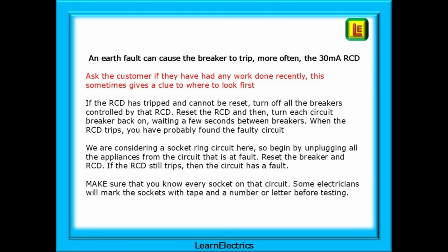Then turn the RCD back on. Then turn each circuit breaker back on one at a time, waiting a few seconds between breakers. When the RCD trips, you have probably found the faulty circuit.